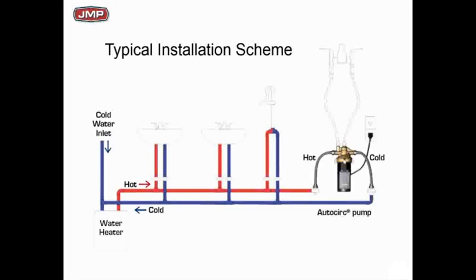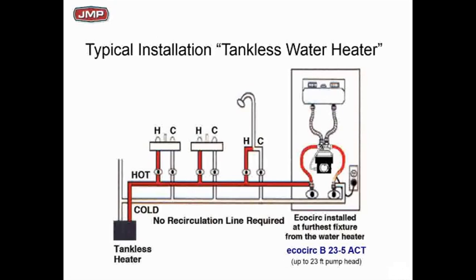This also comes on a time clock. If you want to have a time situation, you can time it at off hours or whatever you want to do. This is some new technology, kind of a point of usage, but it also will maintain hot water to all the fixtures going out there. So if you put one at the end, it does away with the domestic hot water recirc pipe. Great idea for fixing problem jobs you may have. Here's another little snapshot showing showers and how it fits underneath the sink. You will need a power supply out at that last fixture to plug it in, 110.